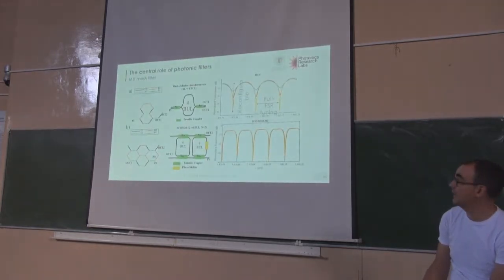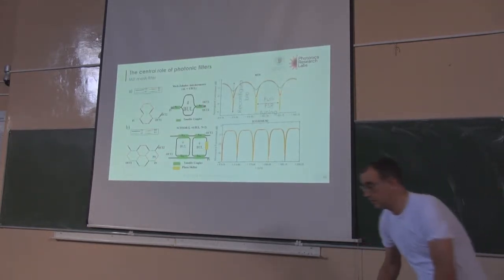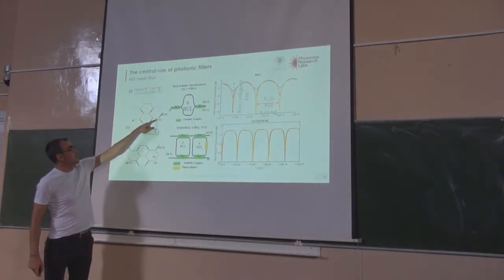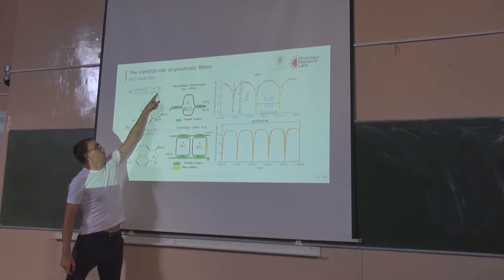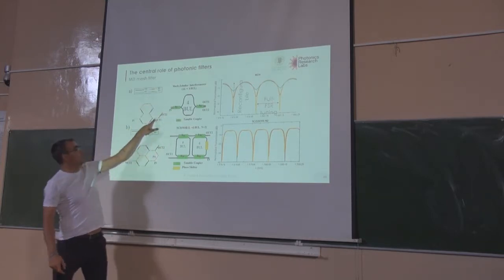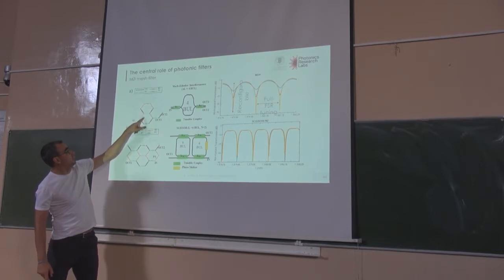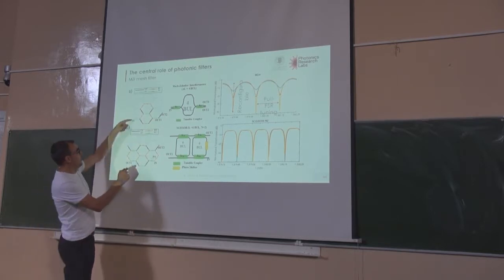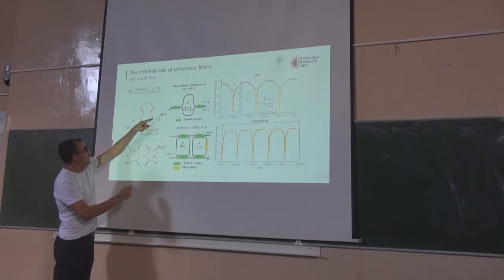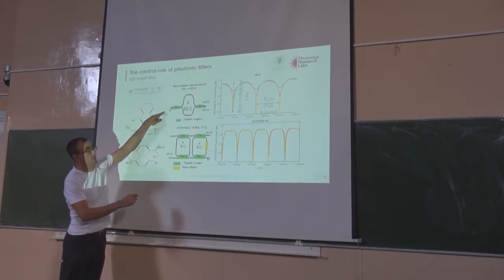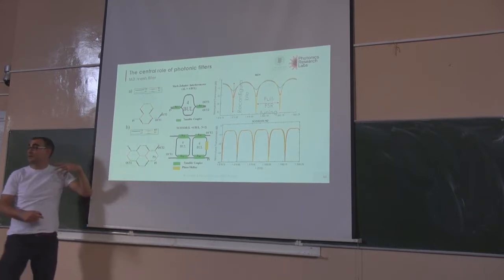With this mesh, you can make, for instance, a Mach-Zehnder, because you set this Mach-Zehnder and this Mach-Zehnder in tunable mode, as a tunable coupler. These are in cross states, and these are in bar states. So actually, you have this path in, and then short arm, long arm, and then out. One and out two. Okay, that's a Mach-Zehnder.